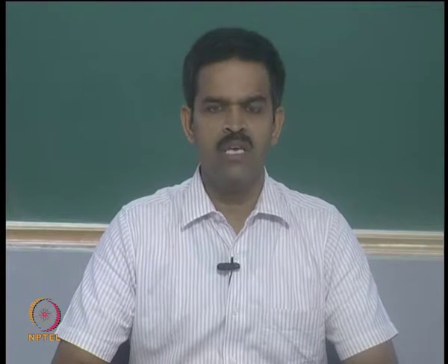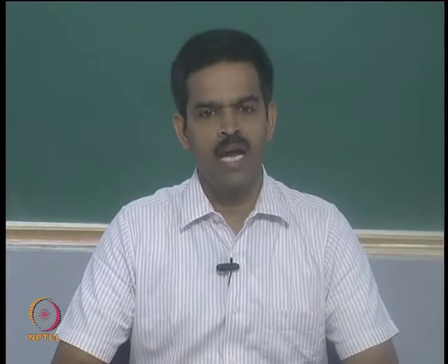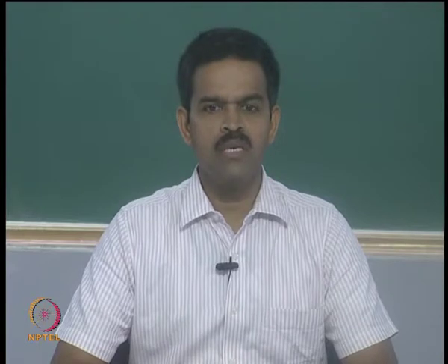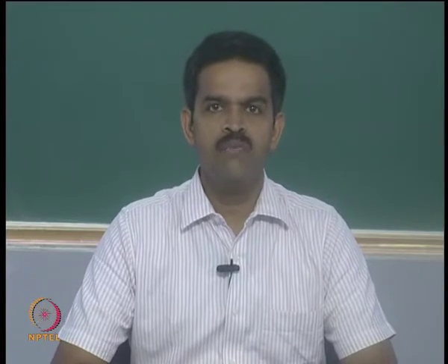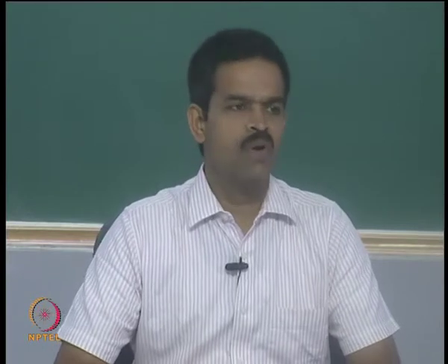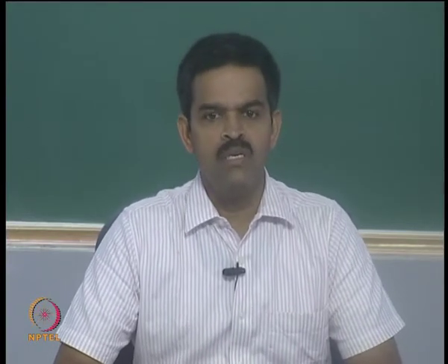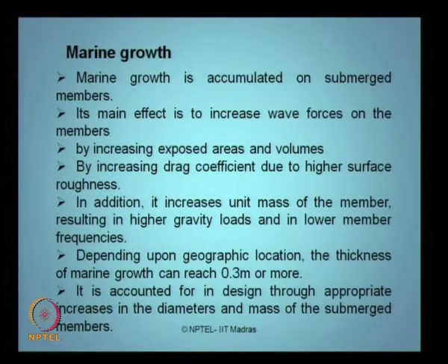So, this is caused essentially by increasing the exposed area and the volume, and it also increases the drag coefficient due to high surface roughness. Ladies and gentlemen, as we all understand, the drag force coefficient depends on the roughness of the surface of the member. In addition, when there is a marine growth deposit around the circumference of the member, the mass of the member is also changed, it further increases. So, this results in higher gravity loads and lower member frequencies. Marine growth has many direct and indirect implications.